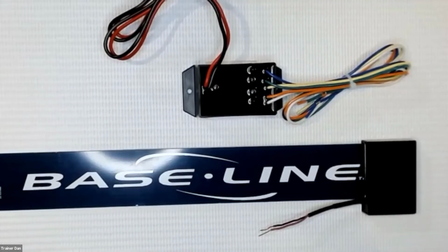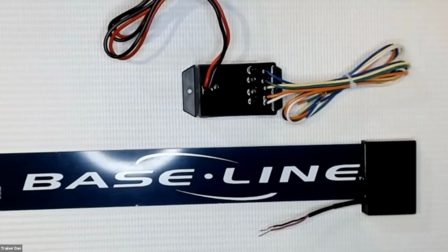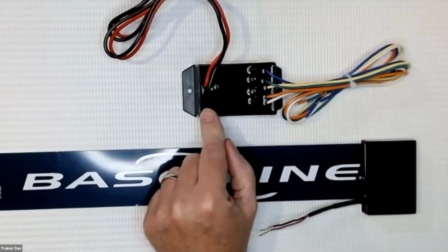I don't know. Clarify that for me. I know it tells me we're having power. I think it also tells us we have communication. And would you turn that into a statement for me? Well, if it's blinking, you've got power to it. Of course, we know I have power. Sure. Then a way to test if you've got communication or data would be to go to the controller and do a self-test for that device based on the serial number associated with that decoder. If it comes back and it sees it, then you have data as well.